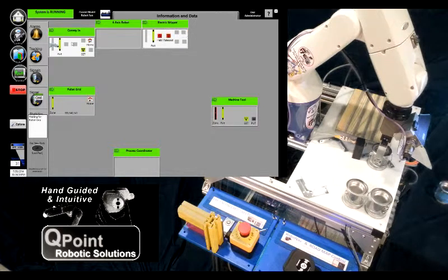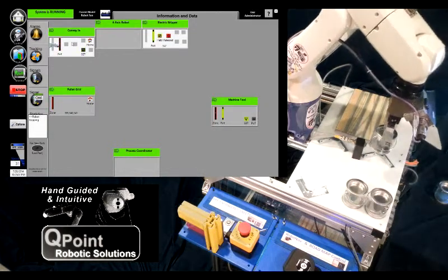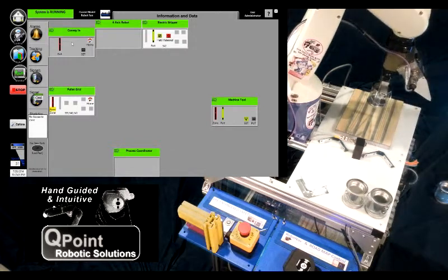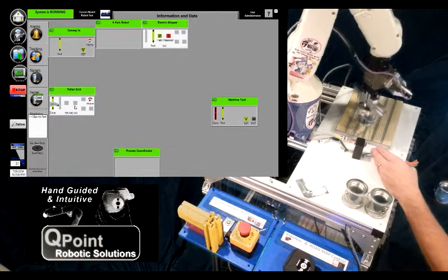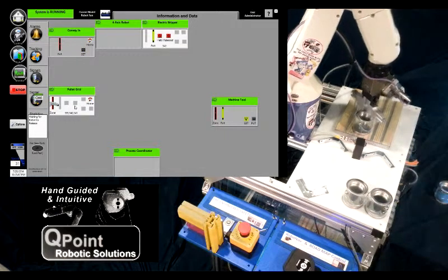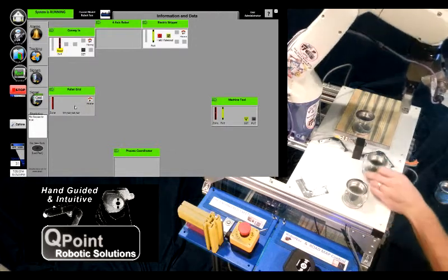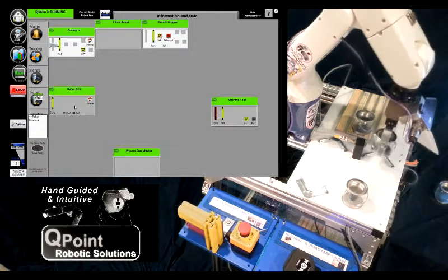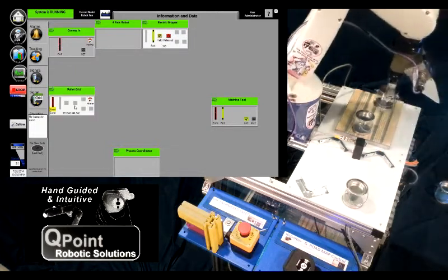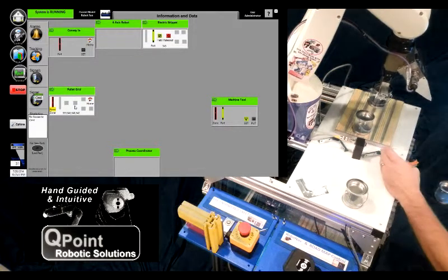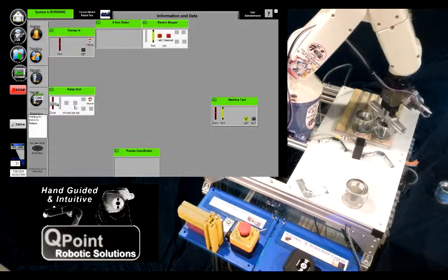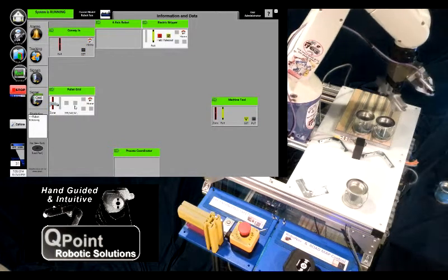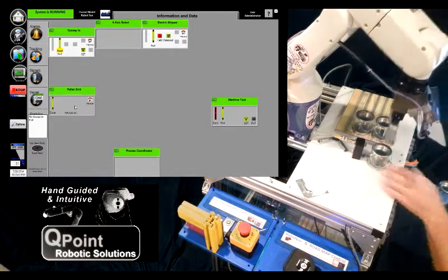The part's ready. Go ahead and pick it up. Go through the home position, you have all the proper approach into the pallet, and you can see at the pallet we need access to the zone. And so once it gets access to the zone, go ahead and drop the part off in pallet position 1. And then we'll come back and repeat. So we've got 2 in position, come back and grab the 3rd.